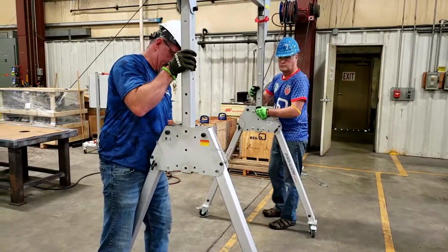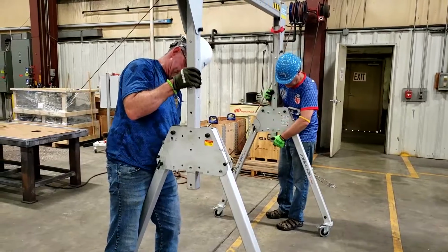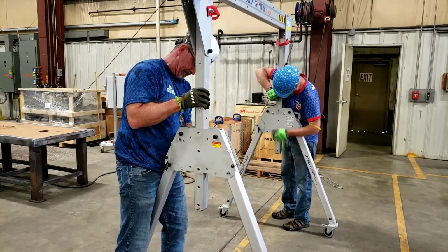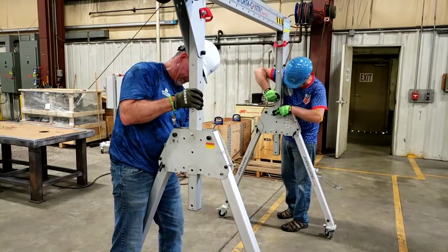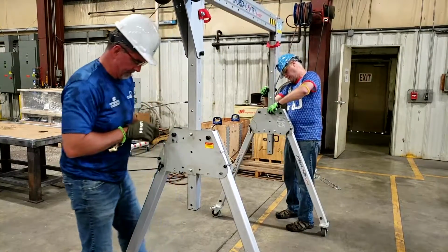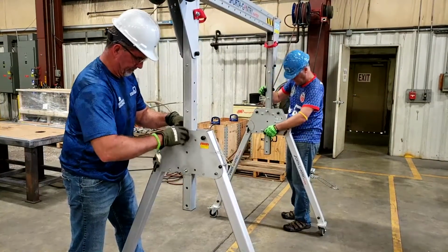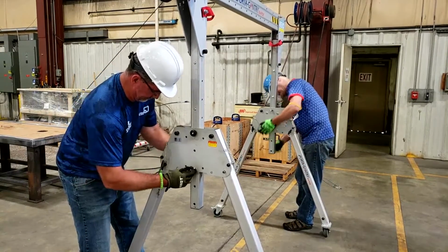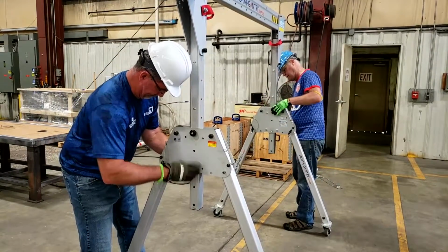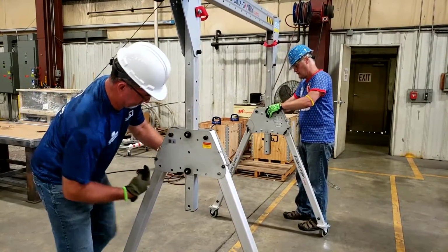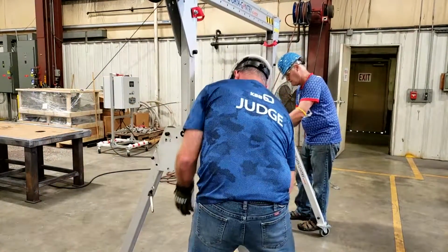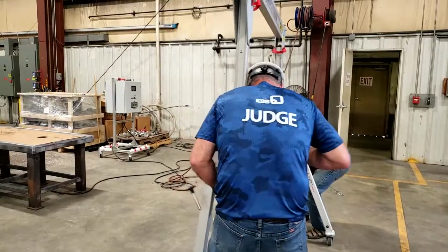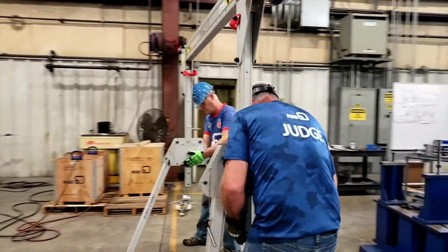Lower the gantry to the proper level with 2 holes visible at the bottom and reinstall bolts hand tight. Bolts shall be installed in the top and bottom holes, leaving the middle one open. The black nuts shall be installed facing outward as defined when the gantry is fully assembled, and the bolt head will face inward.